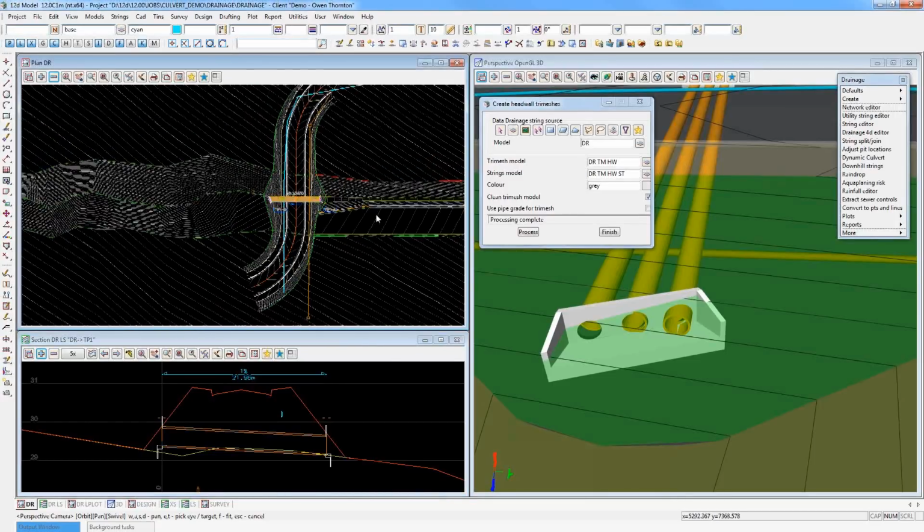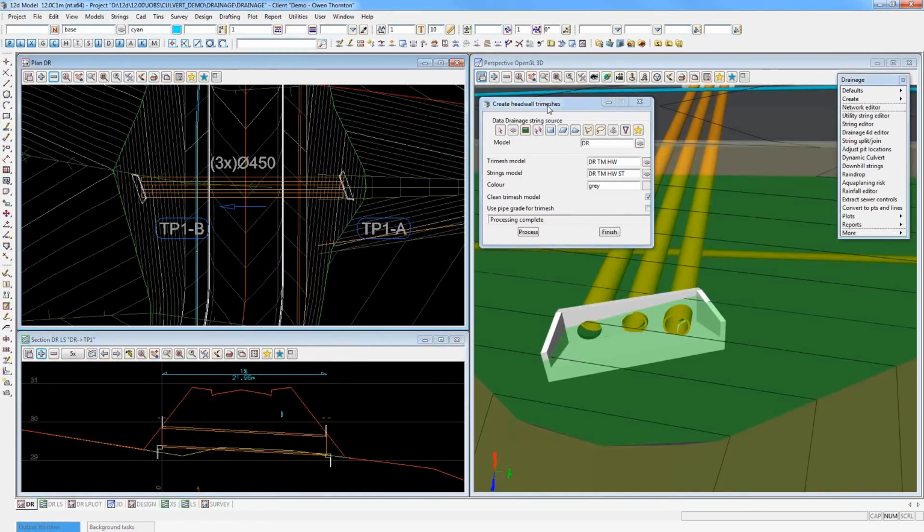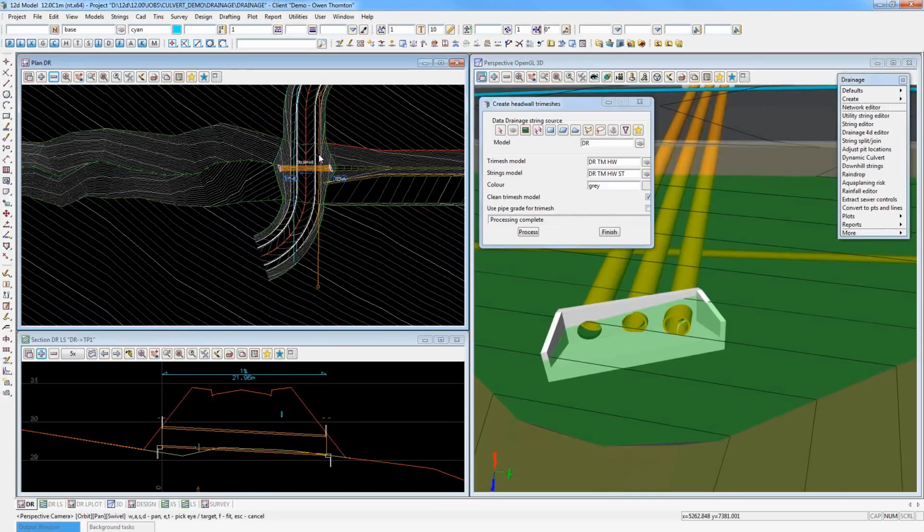I didn't do that in this instance mainly because this brand new culvert head wall macro only supported the head walls where the flow direction was same as string direction. So I was quite careful in that case, but that's just a minor issue. That's a teething problem, I suppose, with this macro that we will get addressed. It's quite embarrassing in a demo if your head walls face the wrong way, so I was careful to avoid that.